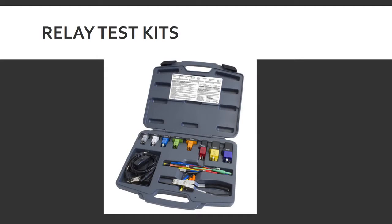Now there are relay test kits out there. These test kits make it easier for you to check the relay while it's on the vehicle. So in essence, you pull the relay out, you place this tester in between the relay and its socket, and then you have terminals that you check without having to back probe. On certain vehicles, it's very hard to back probe the relay, so these adapters come in very handy.